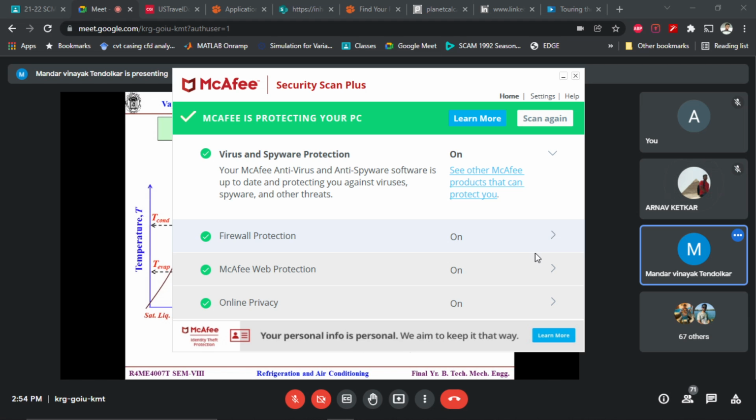Yes, sir. So now you substitute COP of VCC. This is Q evaporator of the VCC cycle divided by net work for the VCC cycle. Here you can observe that Q absorbed in the Carnot and here it is W net in the Carnot cycle. What I'm interested in is this area part, something which is more like a rigid part, stringent. We cannot play with it as we want. Correct?